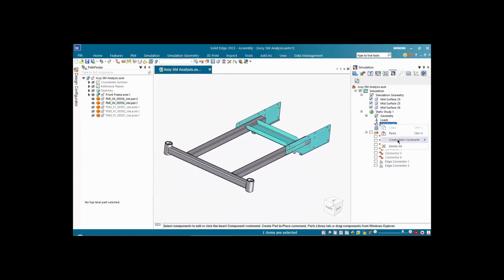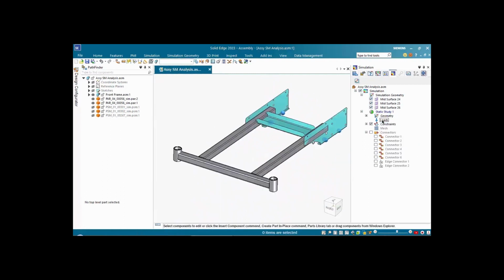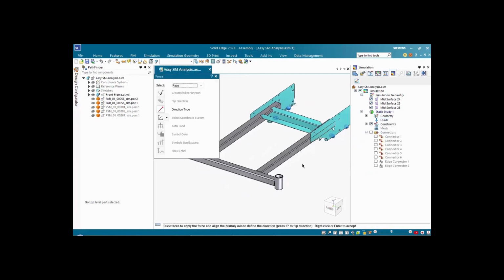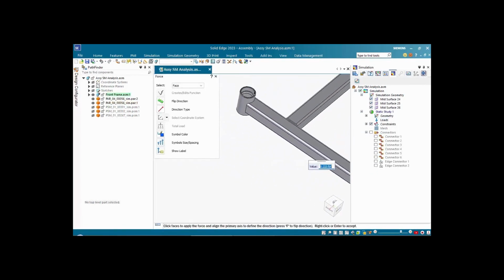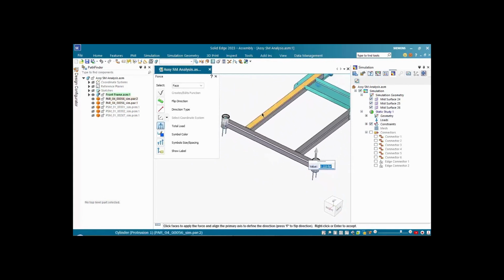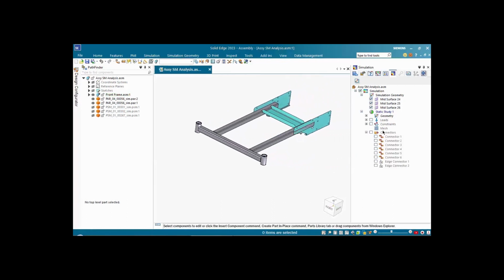We're going to hold this frame from the bottom, the load. The load is going to be placed on these faces, these two faces. So that provides a really convenient way of changing orientation with just one button click. And we're going to apply some load. So let's go mesh and solve.